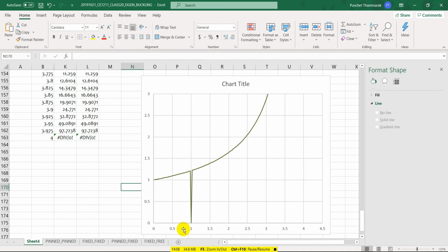You will get more than 1.0 because you magnify the deflection by the compression. Whereas for the tension cases, you have less than 1.0 because the axial tension helps stabilize your structure and reduces the second order effect, reducing the deflection.